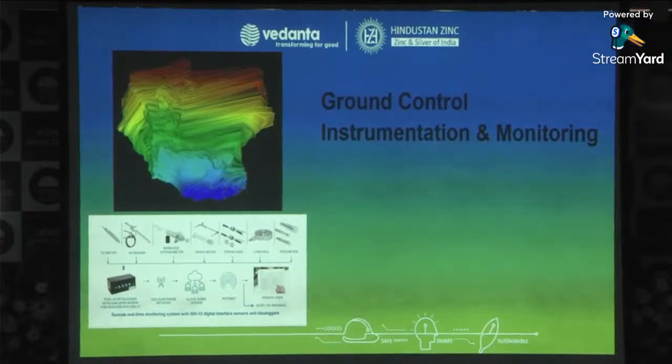Sir, bolting will not be done because, sir, whenever we start dealing with water it becomes slurry. Yes, friction support, sir, friction support. The diameter of the hole is somewhere around 38 mm, sir, and we are sending a 47 mm split set into that, so it expands and gives confinement to the side wall.